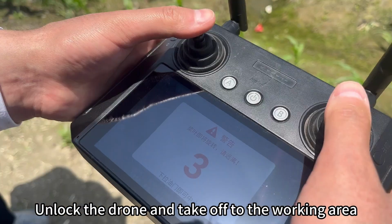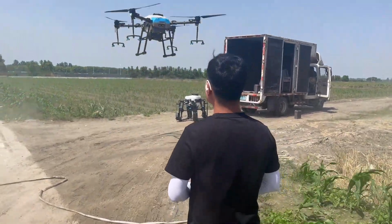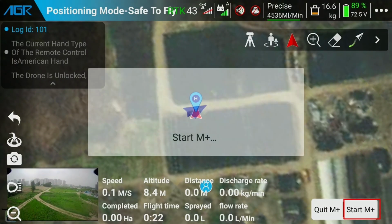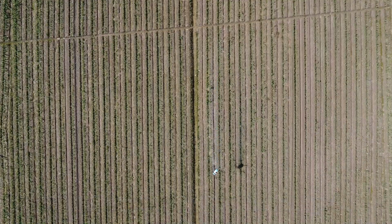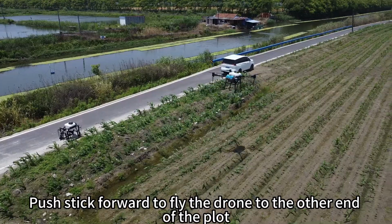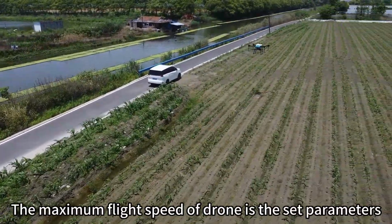Unlock the drone and take off to the working area. Click start operation. Click lock direction. Pushing the stick at this time will not change the flight direction. Push the stick forward to fly the drone to the other end of the plot. When flying with the stick pushed to the maximum, the flight speed of the drone is the set parameter.